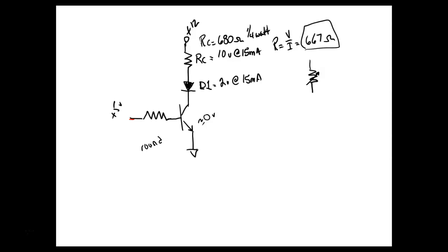Okay. So 680 ohms, quarter watt, we're okay. Now what we need to know is we're going to get about 15 milliamps over here. 15 milliamps is okay. We know we're going to use, now we got to figure out what transistor it is. So what ratings of the transistor are we looking at?